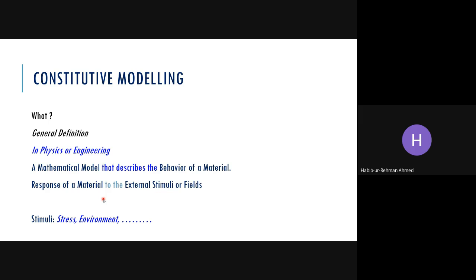One is stress, which is a very common understanding, but another one is environment also. Environmental loading is a very common definition now being used by geotechnical engineers, like change in moisture content, change in type of fluids in the soil, change in the level of contamination in the voids present in the soil. So all these external stimuli like stress or environment fall under that one.